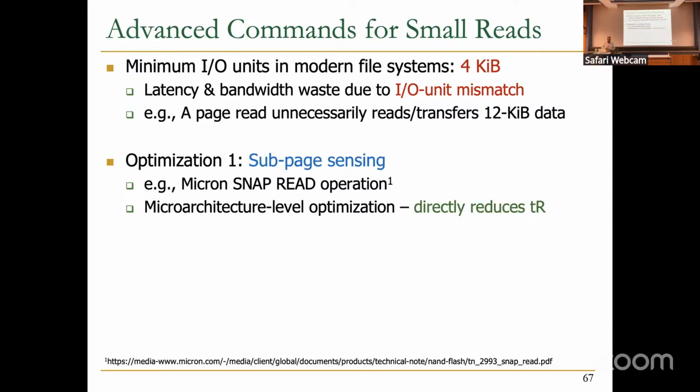For that, there are some optimizations. One is sub-page sensing. It is a patent of Micron, and I think it has been adopted. In Micron, they call it a snap read operation. They changed the microarchitecture and did some optimization, so that you can read only the subpage that you want.